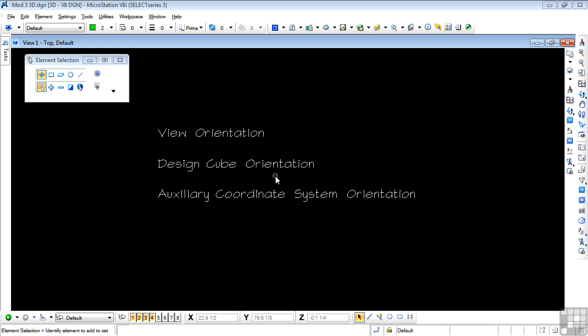When you drew the step block, you used AccuDraw to place the individual elements. At that time, I gave you the instructions on how to rotate the compass to place the elements, but now you need to know how AccuDraw complements 3D drawing in all its aspects. To start, it's helpful to categorize the range of available compass orientations.